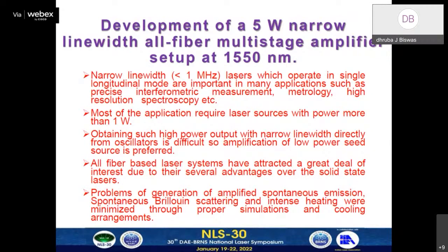This amplifier can be a solid state laser amplifier or a fiber based laser amplifier. We prefer the fiber-based laser amplifier, as it has many advantages over the solid state counterparts. The main problems associated with the fiber amplifier are the generation of ASE, stimulated Brillouin scattering, and heating, which were minimized through proper simulation before the actual design, and proper cooling arrangements were made. Next slide, please.